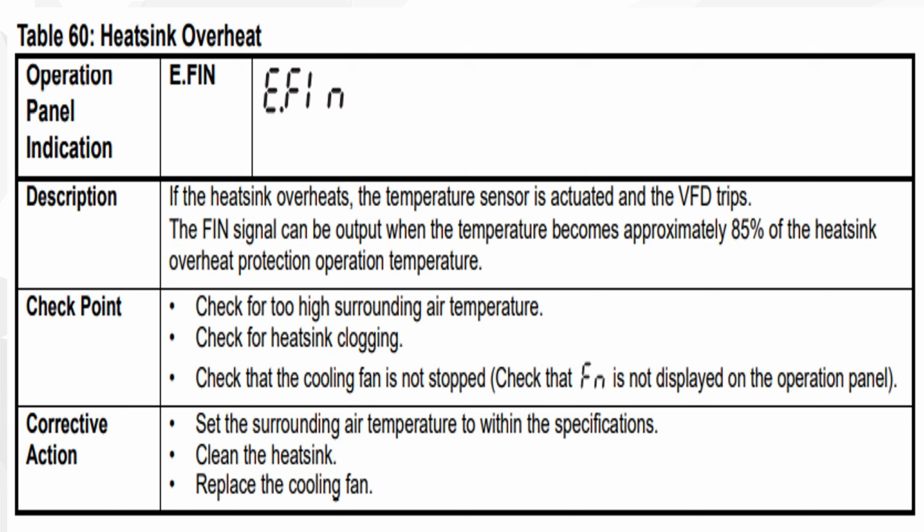If the heatsink is too dusty, we have to clean it properly with a blower. One more reason could be that the temperature sensor is not working or is giving a wrong value. In this case, repair of the VFD is required.